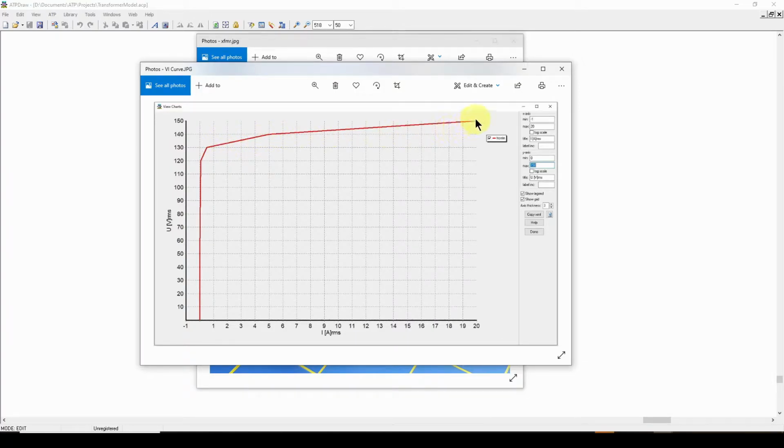Here we just guesstimated our volt-current characteristic, up to around 150 volts, but we're going to verify if that was accurate. We're going to apply some very high voltages and look at the resulting RMS current flow and develop a real curve that we can put into our software simulator.